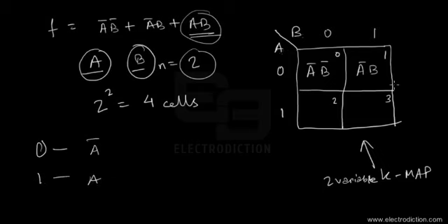Okay, so if you apply your head a little more, then you can see the minterm combination for the cell numbers 2 and 3 respectively. So we can get another combination of minterm over here that should look something like a b bar, and for cell number 3 it would be a b, where both are non-complementary variables. Okay, so this is how the combinations occur inside a K-map.